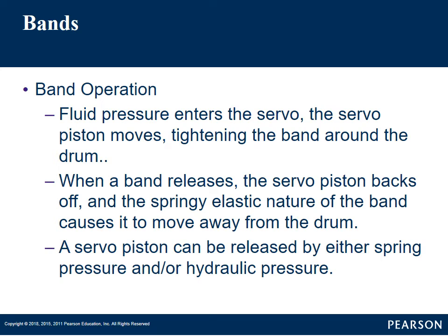And that servo piston can be released by either spring pressure and or hydraulic pressure. Now I'm going to say this, I've never seen a servo piston that didn't have a spring in it. Again, as we've talked about in classes, about the time you say that, a transmission manufacturer calls you a liar and builds one without a spring in it.